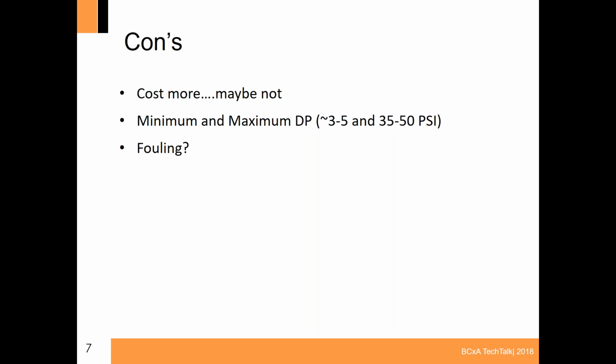In fact, in some situations, we're actually seeing that when you eliminate the labor and the balance valve, a couple of the smaller pressure independent zone valves are actually less expensive than doing it the traditional method. Now, the bigger valves haven't quite caught up there, but we're seeing it on the low end, and that's where you see a lot of the valves, a lot of VAV boxes with reheat or a lot of 4-pipe fan coils. So that cost point is coming down.